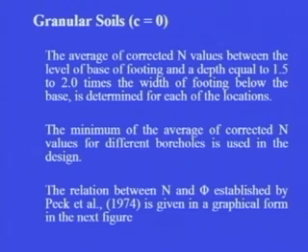As we know, these standard penetration tests are conducted in boreholes, and we advance the borehole maybe up to 12 meters, 15 meters, and at each 1.5 meter depth we conduct this test. So, these values are observed, and the observed values are then corrected for overburden or dilatancy wherever required, depending upon the water table or the type of soil.